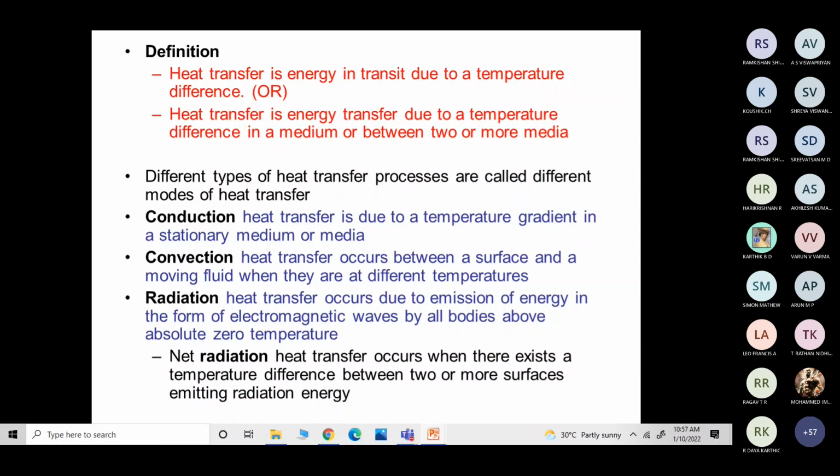Okay, very good. But how does the cylinder get heated? Actually, the process inside the engine cylinder is combustion of air-fuel mixture. Exothermic, yes, sir. So again, there is high heat transfer by means of convection from the hot gas to the cylinder. Cylinder surface to the fin surface is by conduction, and from the fin surface to the upcoming wind or air is again convection. Convection, conduction, and convection.